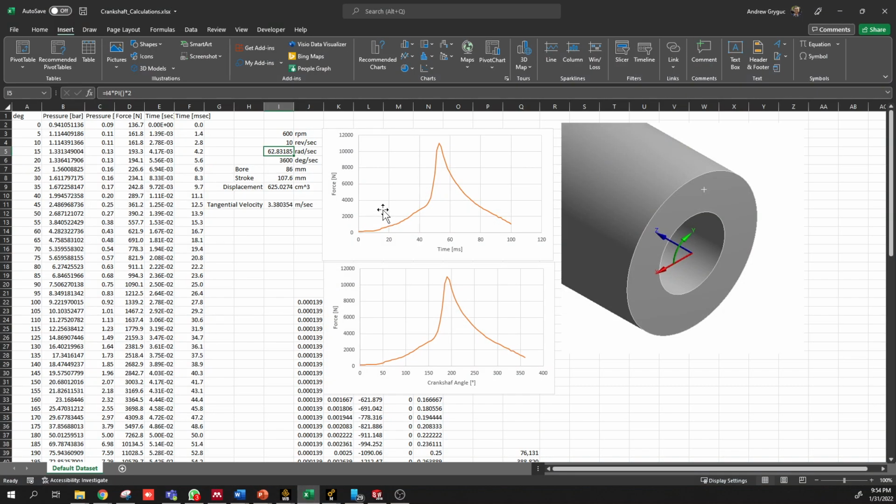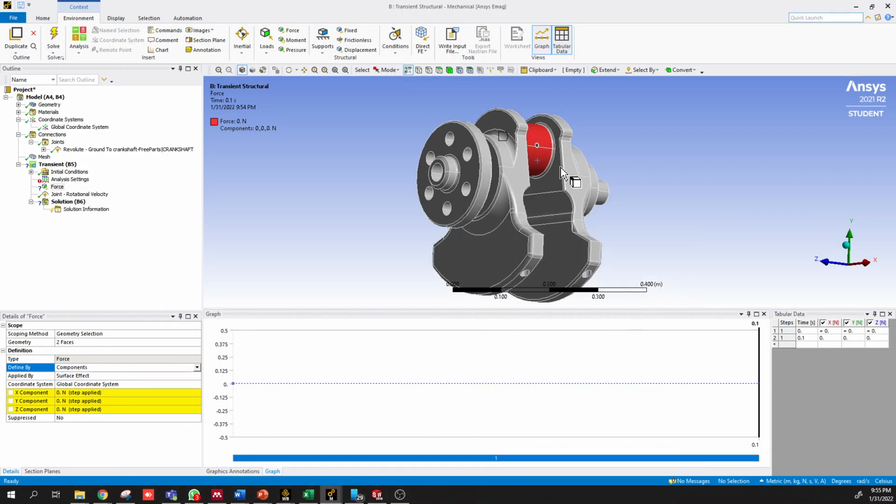We don't have any information on the connecting rod length. So in order to find the X and Y components of this force, we'd have to know the connecting rod length to get a free body diagram and find the X component. We're just assuming it's all going to be in the Y direction because we're making that small angle assumption. If the connecting rod is very long, that would be a good assumption, but I encourage you to do X and Y components, or in this sign convention here, it would still be X and Y.